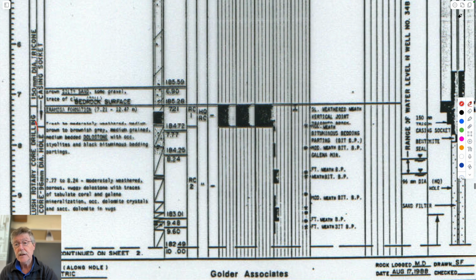It looks like it has a piezometer tube go inside it, so a piece of 1-inch piping, just like you'd have in your house, PVC piping, that goes down into the bottom of the wellbore, is grouted by pouring concrete, a slurry of grout in here that seals off this tube from anything outside here. And at the bottom of this tube, you'll just have a number of hacksaw cuts in it to be able to let water into it.